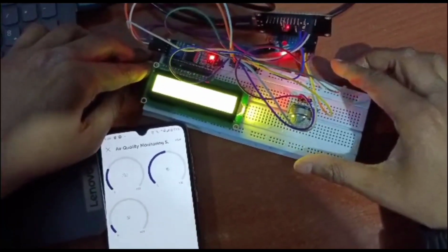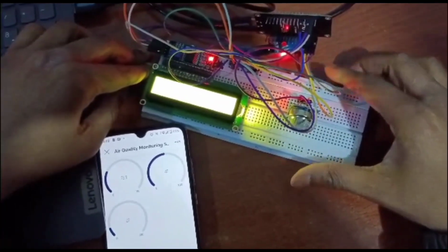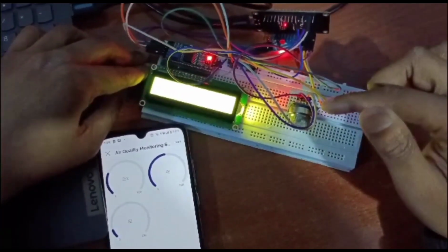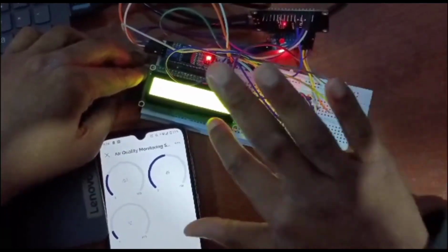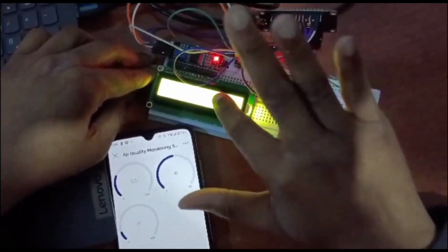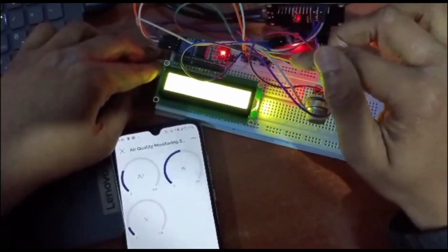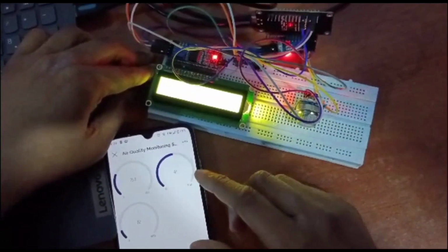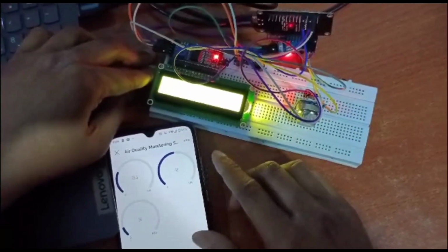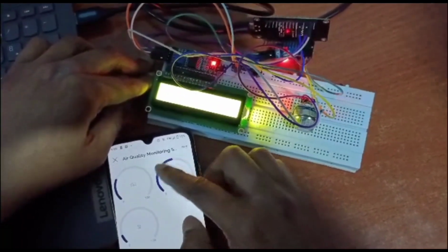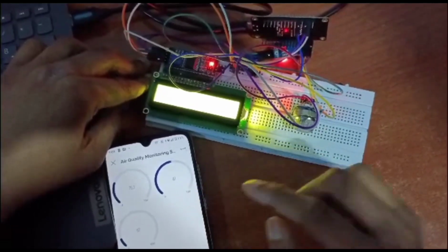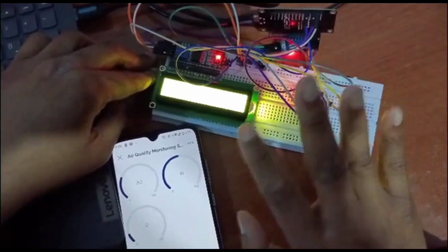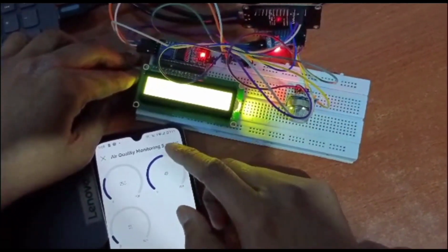Now the overall result of the project is that the system continuously measures the air quality, temperature, and humidity. The readings from the sensors are displayed on the LCD screen using the I2C converter. The ESP8266 board communicates with the Blynk platform to send the sensor data wirelessly to a mobile, where it is displayed on the mobile screen. Additionally, if the air quality exceeds a certain threshold, an email alert is sent to notify the user about the poor air quality.